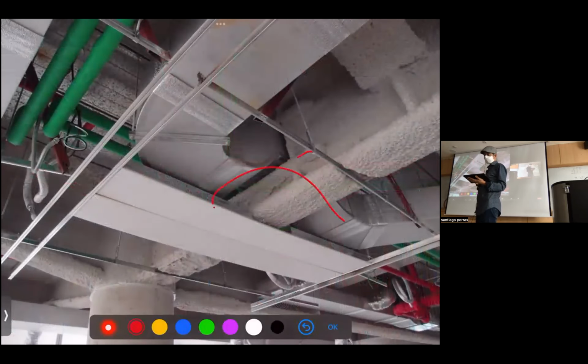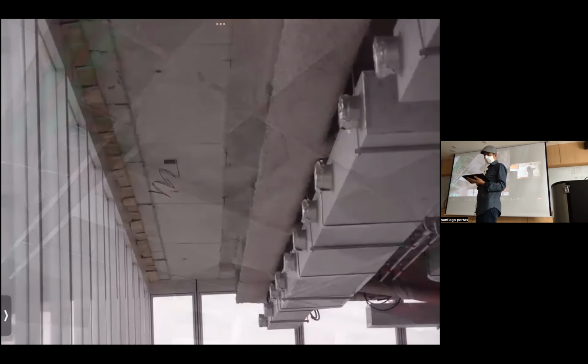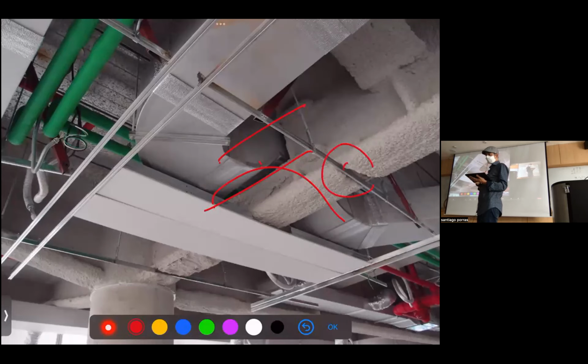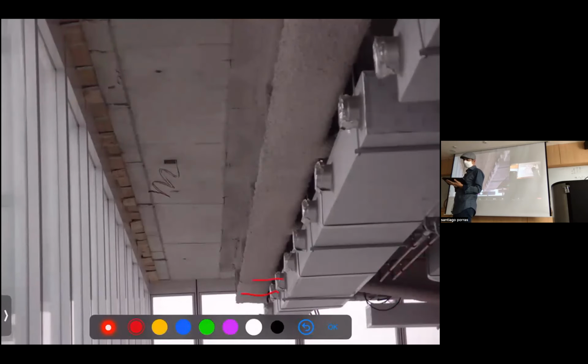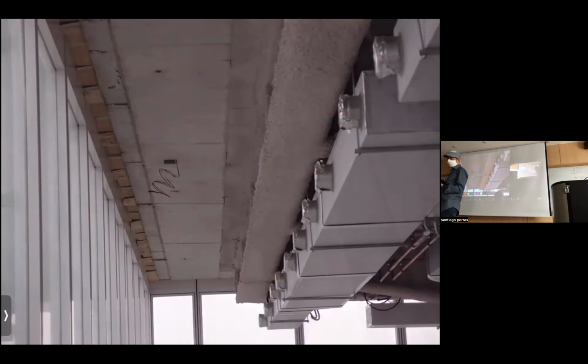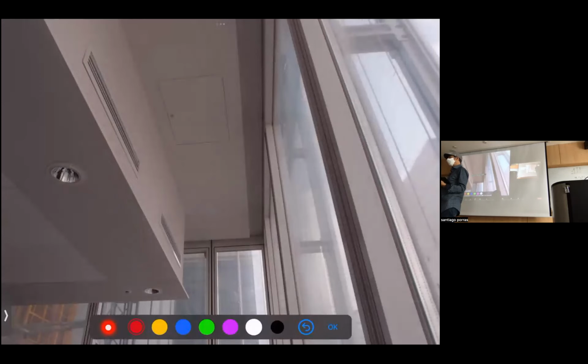This is the conflict, right? Even with the structure. And you see the fire protection is broken. So in case of fire, this will be a weak point. Be very careful with those. And then this is very high quality: many outlets with very long diffusers. So you will not feel the air moving, not even the sound, because you have a big volume with very small speed. And this is how it ends, right? So instead of those concentrated outlets we have, long elements give less air speed and less noise.